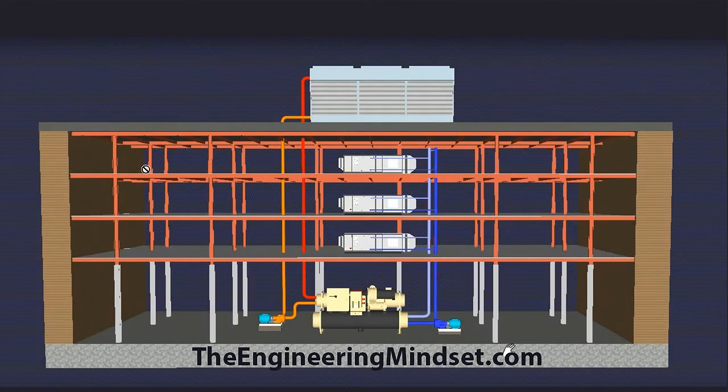The air within this space needs to be conditioned, so there's a fan inside there which we'll also be looking at, and that's going to suck the air from the office into the AHU, and that will then cool it down and may heat it and may humidify it, and it's also going to filter it and check that there's enough fresh air in that space as well. And then that air is going to be pushed out onto the floors through the ductwork. I haven't shown the ductwork on this, but you'll see an example shortly.